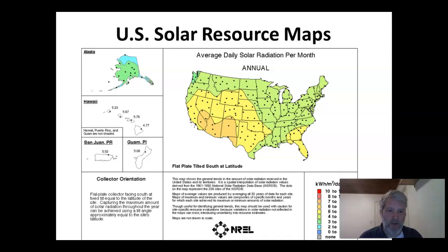So let's say that you have a solar system, and it's a 10 kilowatt solar system, because the math on that is really easy. So let's say that it has 10 kilowatts, and that is the peak rating. And annually, we want to find out how much energy that thing is producing in Portland, Oregon. Well, we would take the 10 kilowatts, we'd multiply it times the 4 suns, and we would get 40 kilowatt hours per day is what that system is able to do.